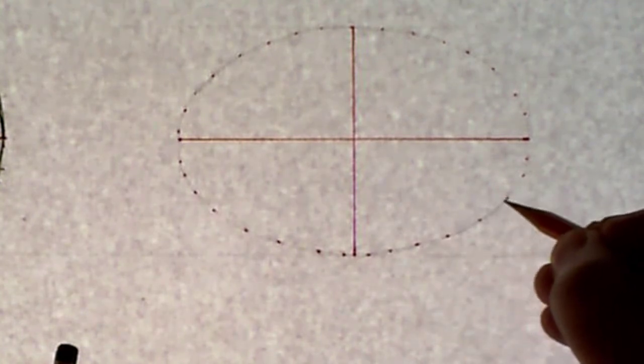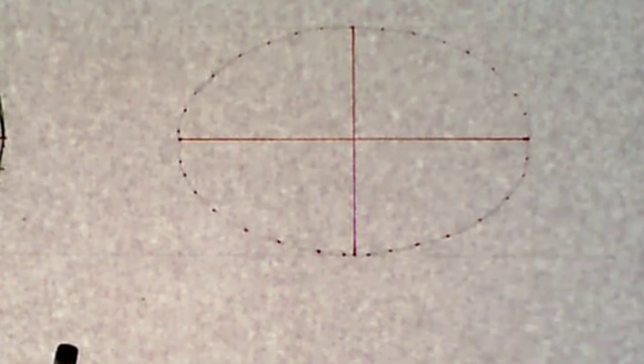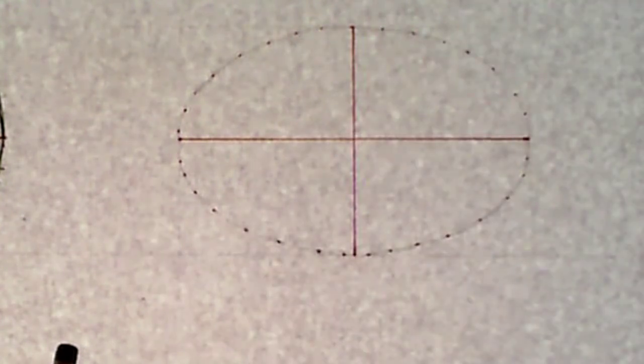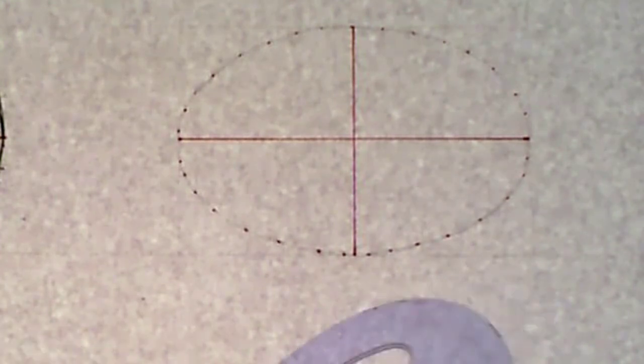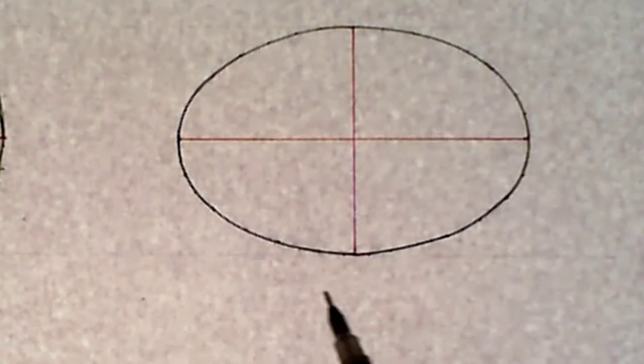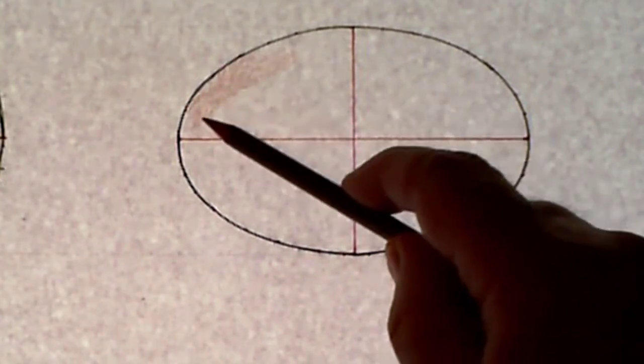Now, for me personally, I think this is the most accurate way of drawing an ellipse in technical drawing, because you establish as many points as you want in order to establish the true shape of the ellipse. Now, I'm going to draw the result of the ellipse in black ink, using a French curve. So that is my ellipse drawn in with black ink, and again I'm simply just going to shade the ellipse in brown with a brown colouring pencil.